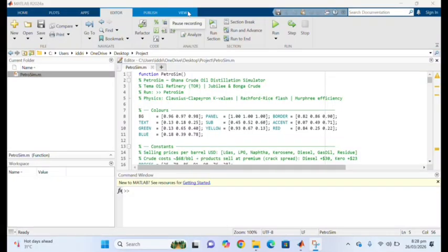Then we simulate the column tray by tray to see whether vapor moves up or liquid flows down until the system stabilizes. We've also included tray efficiency, calculated using the Murphree tray efficiency equation, to reflect real-life conditions since industrial equipment isn't perfect. And finally, this program generates graphs showing temperature, composition, and energy usage across the column.